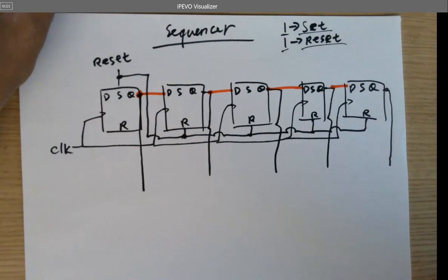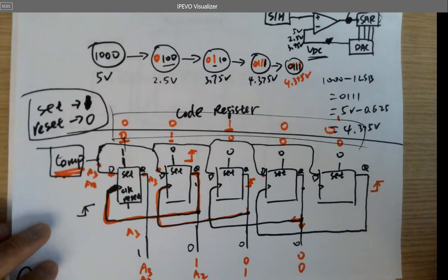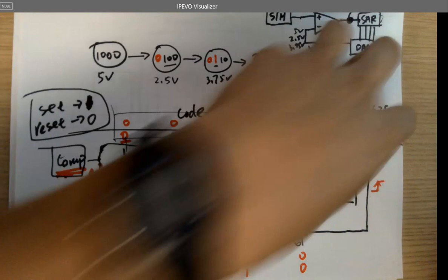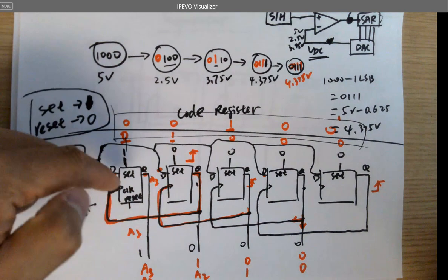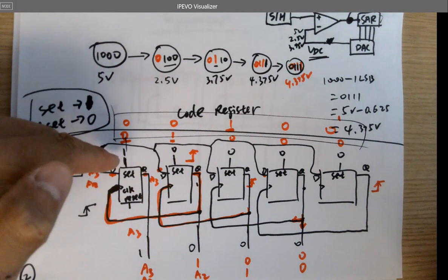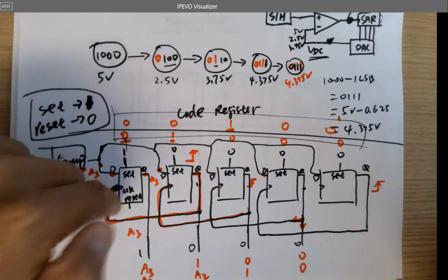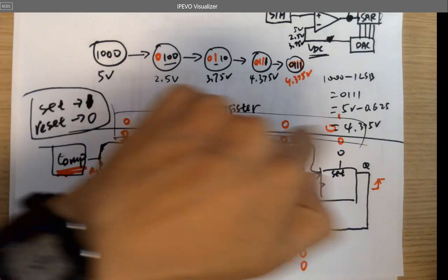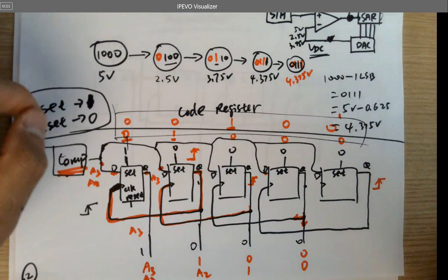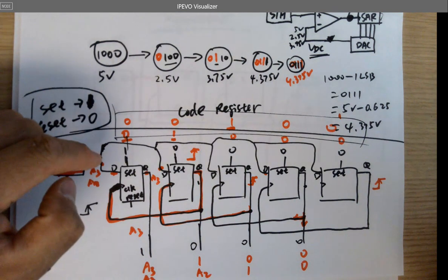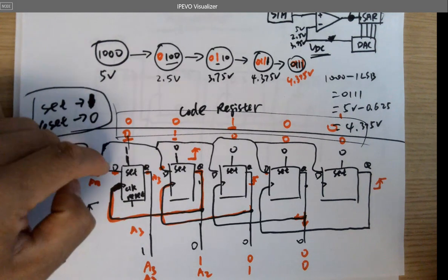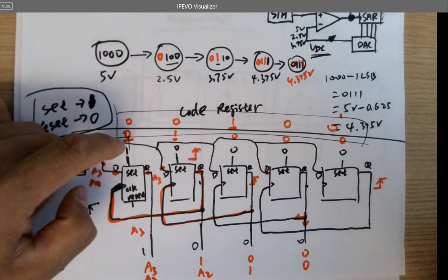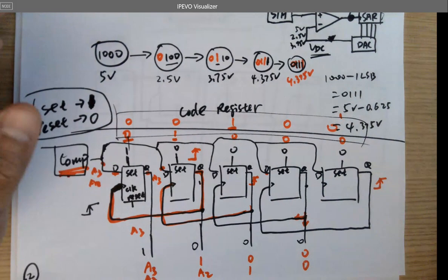So that whatever circuit is on the top should feed 5-bit digital data to the bottom circuit, starting with 1 0 0 0 0. And every cycle it should shift that 1 to the right and replace that 1 with a 0. That's what we want. Okay?